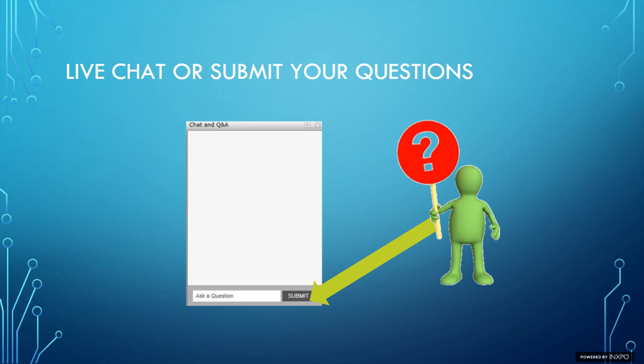Yes, the easiest one is pressure dew point, no problem. The requirement was annual or biannually that they do make a full test, which is also oil and particulates. The oil, depending on what your level is, it is easy all the way down to about 1 ppm. Anything below 1 ppm is not going to be that easy. Then you're talking about $10,000, $12,000 for an online sensor.